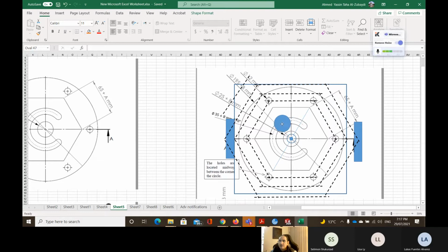Then we make a G03 to this point, then G03 to that point, because the G03 or G02 cannot cut more than 180 degrees perfectly, so it's better to do it by steps. To cut it in half, we move to here, 135 degrees, then another 135 degrees, and then we finish the work. Then we go G00 to the height of Z equal to 5.